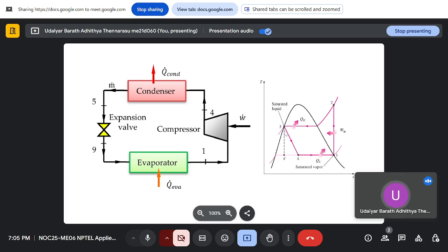But you are losing some of the refrigeration because of that. There is some exergy loss by doing an isenthalpic process, which is given by this area 3, 4, 4 dash and so on, which will cause an exergy restriction, which is putting in more work, because now it's not constant entropy.